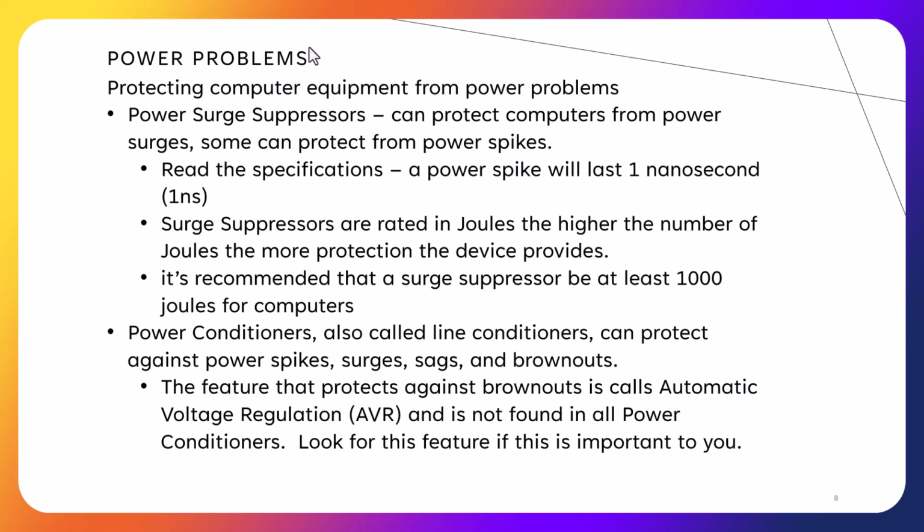You also want to see how much power it can handle. Surge suppressors are rated in joules, and if you're going to get a surge suppressor for a laptop or a PC, try to pick one that will handle at least 1,000 joules for a system. If you have more than just a PC and a couple monitors, you can probably increase that, but you want it to at least handle 1,000 joules for a standard PC.